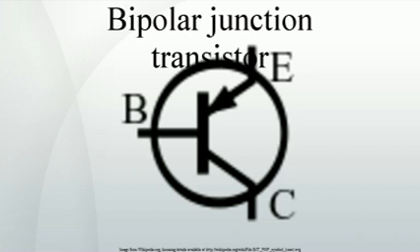These electrons diffuse through the base from the region of high concentration near the emitter towards the region of low concentration near the collector. The electrons in the base are called minority carriers because the base is doped p-type, which makes holes the majority carrier in the base. To minimize the percentage of carriers that recombine before reaching the collector-base junction, the transistor's base region must be thin enough that carriers can diffuse across it in much less time than the semiconductor's minority carrier lifetime.